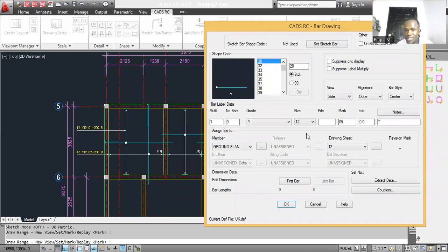From my years of experience, I understand that your distribution bars are just support bars, just to hold down, so it's not doing a major job. Whether your design is saying anything or not, my main bar and my support bar are very important to me, but my distribution bar, which is a nominal bar, I can use Y10. So I always use Y10. I use lesser reinforcement. So I use Y10 no matter what.